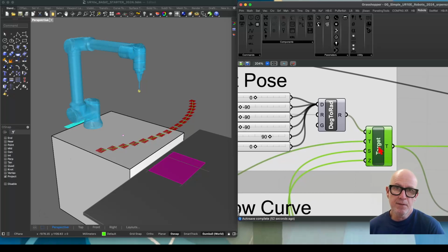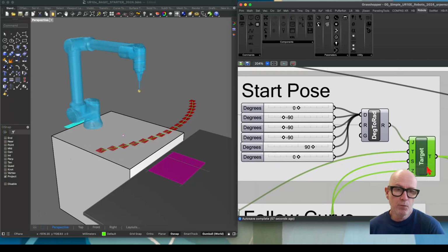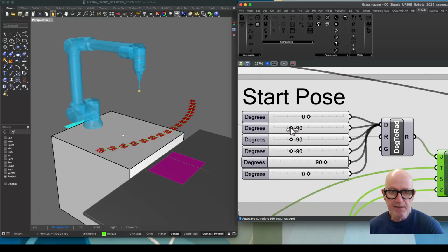It has a lot of options that we'll go into later, but basically everything that we do in robots will be to assign targets to the robot, and that's even when you're just moving the joint rotations. So here we're very explicitly saying that we would like to have the robot in this kind of T configuration when we start, so that we're directly above the surface that we're working with. And I just happen to know that if we set up the base to 0 and then the next joint to -90 and so on, that we will get what's called an on-table kind of T-shaped pose, okay?